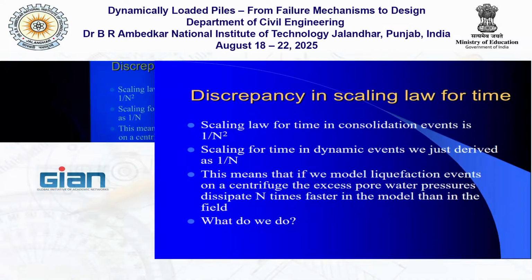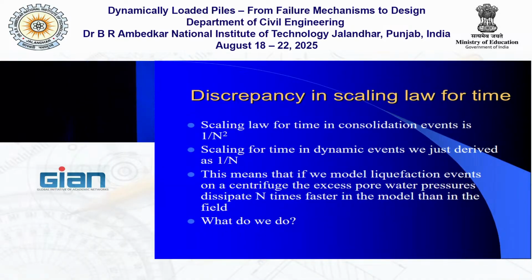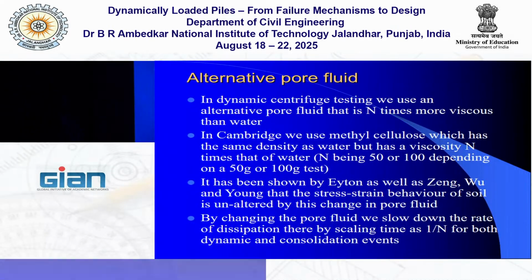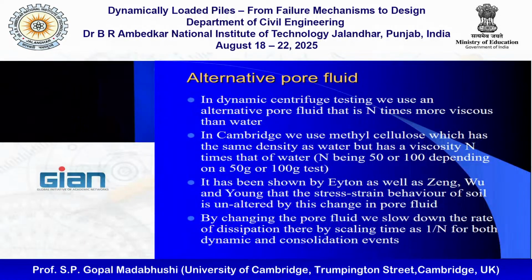What do we do? We have two options. One is we can change the pore fluid. Instead of using water as the pore fluid, I can use viscous liquids. When I started my PhD, we used to use silicone oil. And silicone oil works well, but it's very expensive. It's actually used in medical applications.